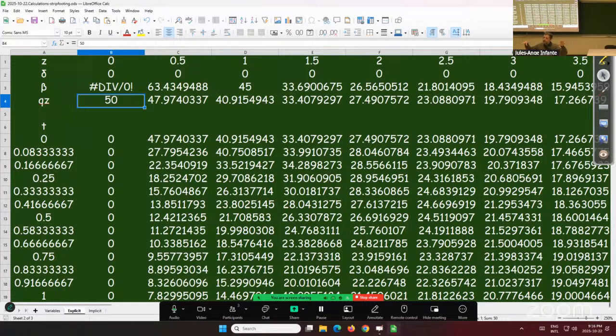Okay, it's better to do hydraulic conductivity tests in the field because you're more likely to catch those little seams that don't show up when you take a sample. You know what you're going to do to take a sample? You clean it up, right? A silt seam won't let you pick up a nice sample, right? Or a sandy seam, it will break at that point.